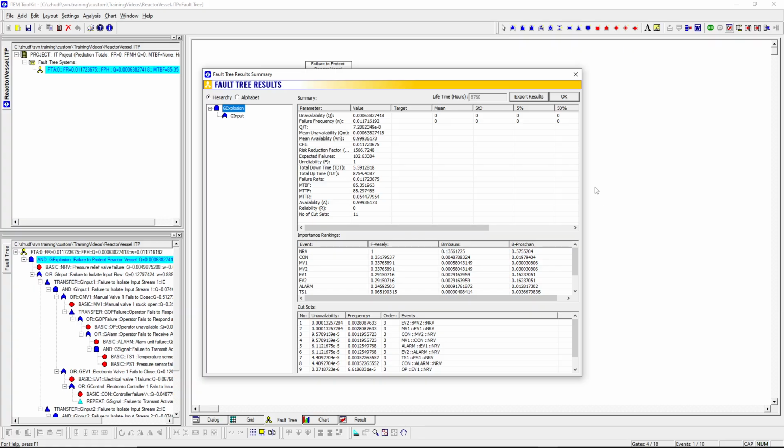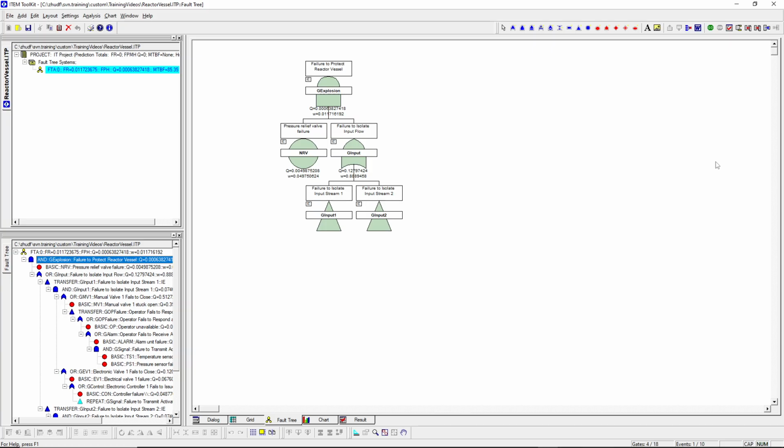failure. While our baseline results look promising, real-world engineering systems rarely operate in complete isolation. Up until now, we have treated our overlapping layers of protection, the automated sensors, the electronic controllers, and the manual human pathways, as entirely independent entities. However, complex systems frequently share common support utilities, such as electrical power, cooling water, or pneumatic air. If a single support system provides utility to multiple independent safeguards, it creates a hidden vulnerability known as a shared dependency or a common cause failure path.